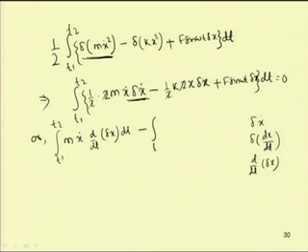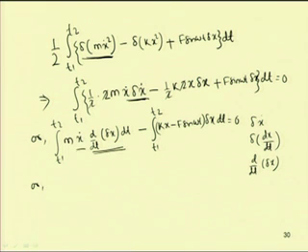Then minus, the 2 cancels, the integral from T1 to T2 of k x minus F sin omega t delta x dt equals 0. For the first part I use integration by parts, with m x dot as the first function and d by dt of del x as the second function.